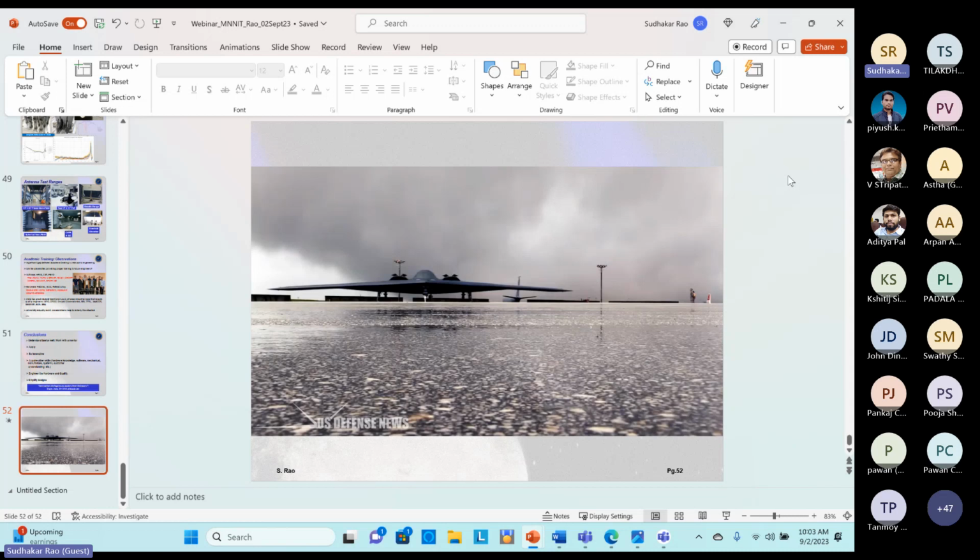Also, a good thing with the integrated approach is any mismatches you have. For example, there's a horn and there is a polarizer. Of course, there's a mismatch between the two because the scattering matrices are different. So with the integrated approach, instead of local optimization, you can do global optimization and get your hardware much more working, meeting the requirements, better RF. You can also make it compact because you have fewer flanges, flange attachments.